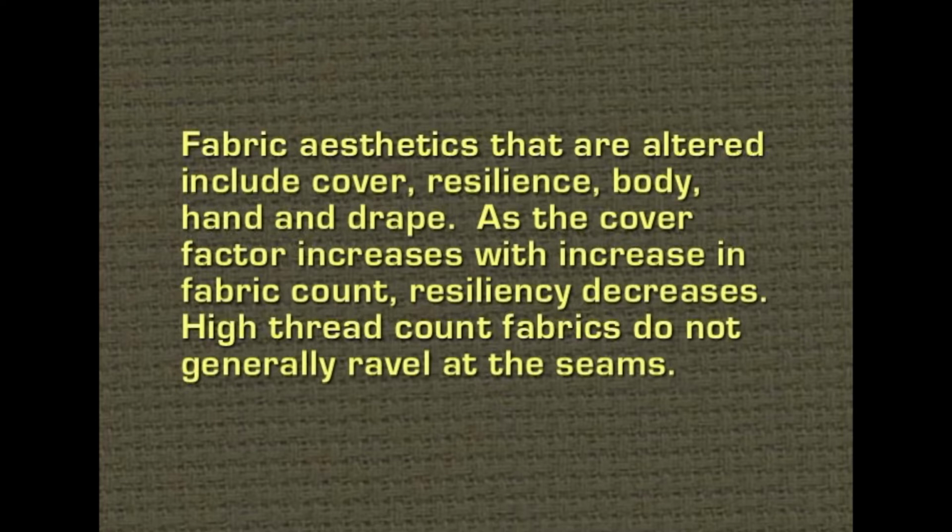Fabric aesthetics that are altered include cover, resilience, body, hand and drape. As the cover factor increases with increase in fabric count, resiliency decreases. High thread count fabrics do not generally ravel at the seams, which is an important aspect for ready-made garments.